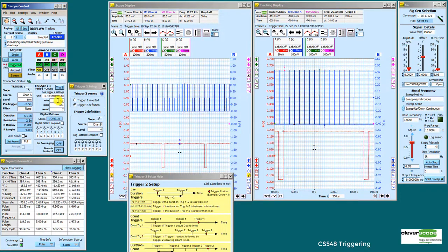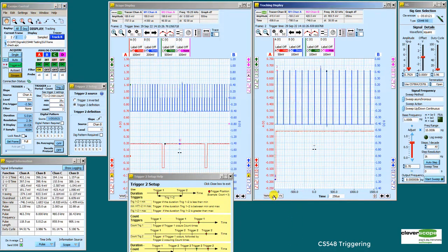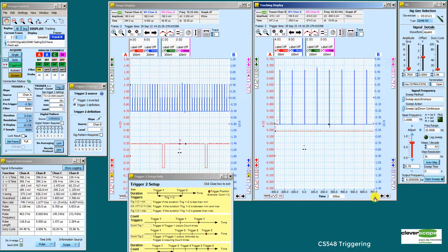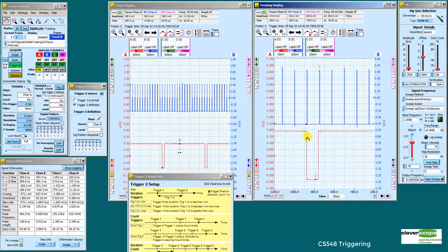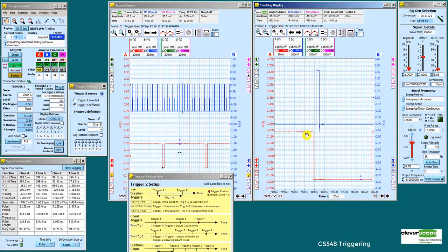If we make this a bit narrower, make that say 20 microseconds, and look at this gap here. We can see it's less than 20 microseconds, and if we make it even smaller, like 1 microsecond, it's not going to happen very often, I would think. There we go. So we can check that the signals are coherent before we start counting them,